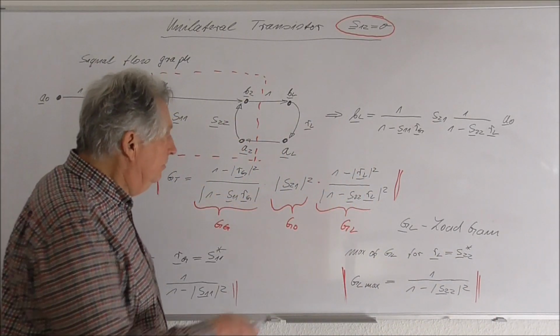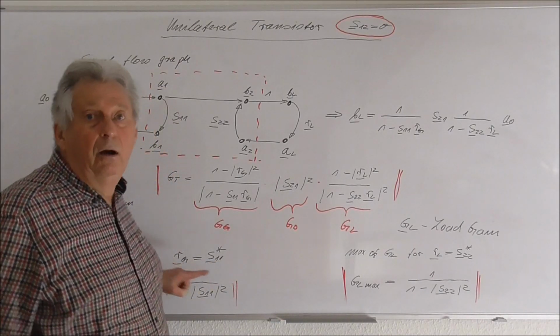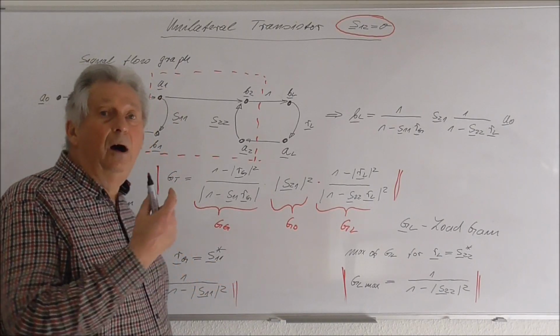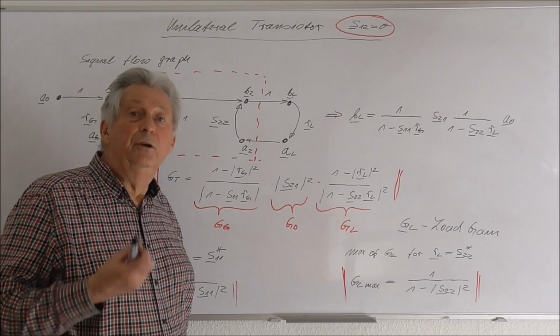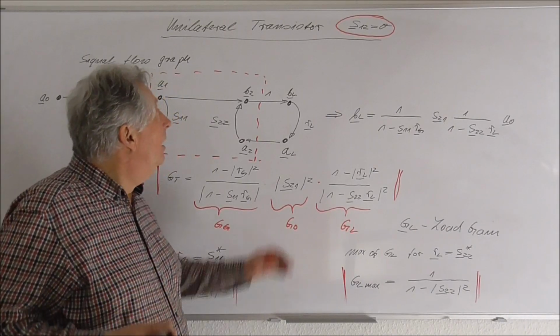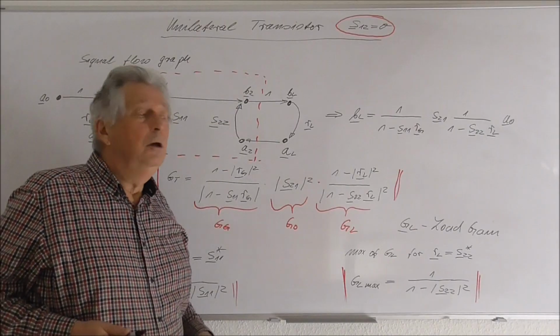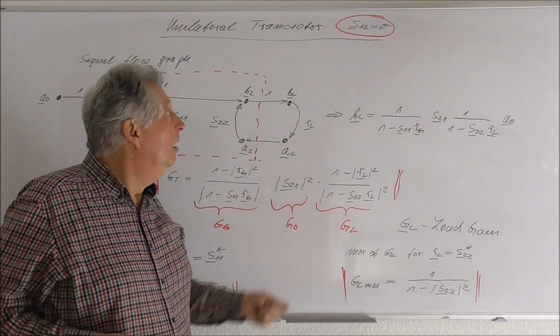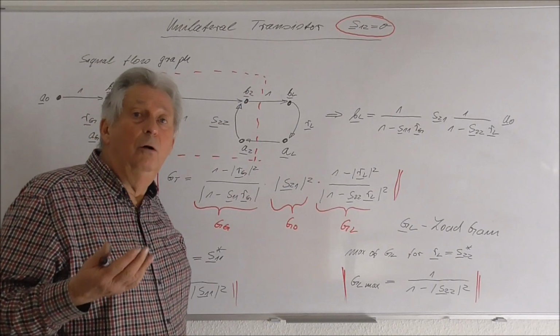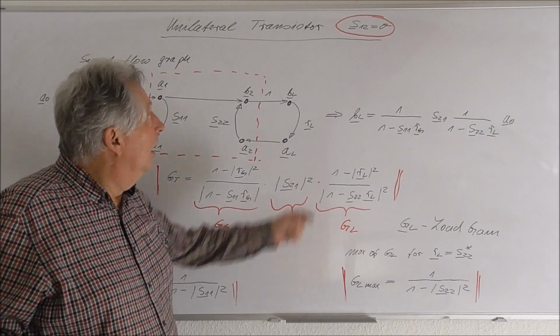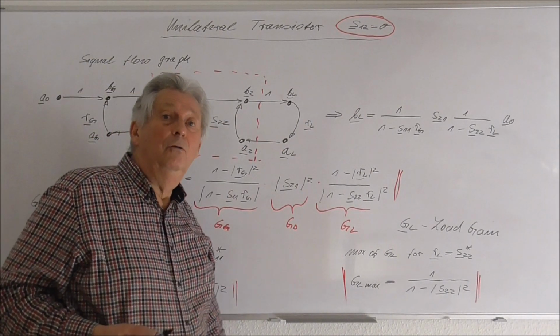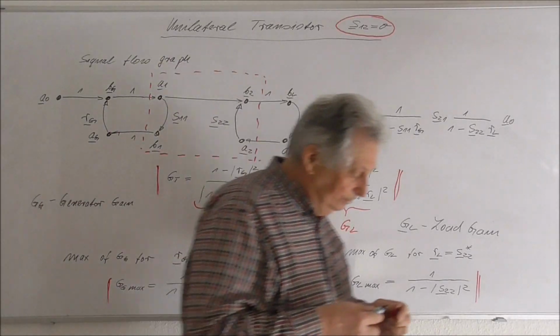So now these two conditions already define us now the setup of an RF amplifier as soon as we have a unilateral transistor which is stable over the whole frequency range and which has no feedback from the output to the input.